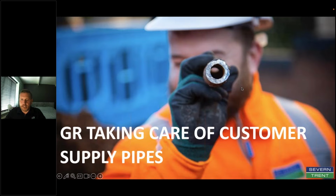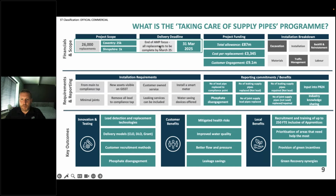I've got a slide next, I think, which will give you a bit more detail. This is a breakdown of how many supply pipes we're going to do. In the UK, it breaks down into 3 parts of the pipe. You have the communication pipe, which is from the main, the ferrule, up to the boundary line of the customer's property, the supply pipe, which is from the boundary into the customer's property, and then we call it an overall service pipe, which is both of them added together.